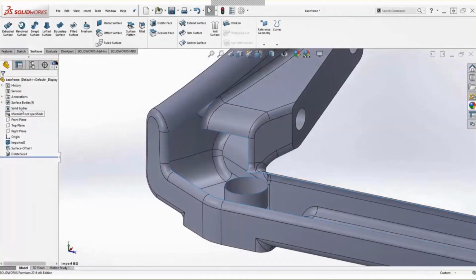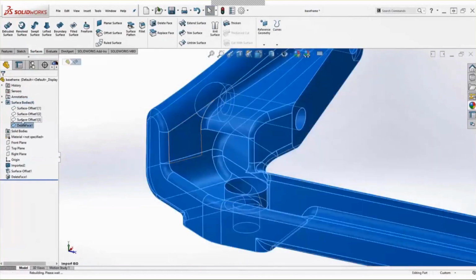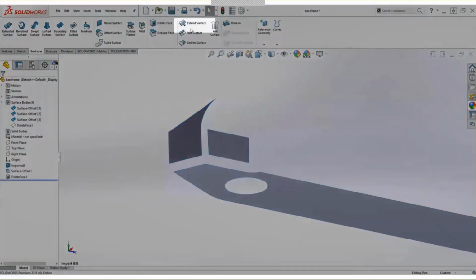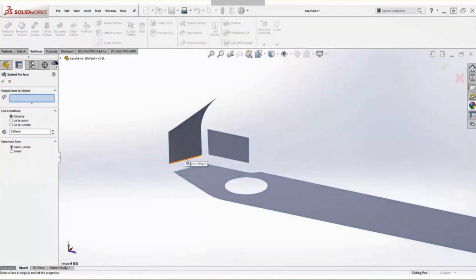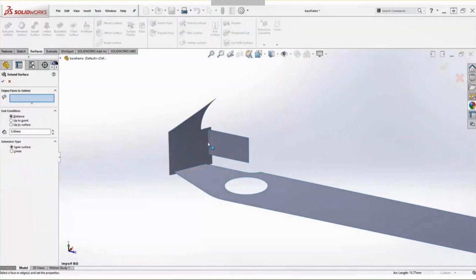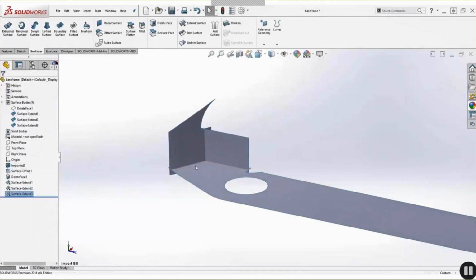And now we need to recreate that hard edge corner. So to do that, we'll need to extend edges of our original surfaces so they all intersect. And we're going to do that using the extend surface command. I only extend the edges that relate to the corner I'm trying to fix so that it'll knit together easily later. And you'll notice that since these are individual bodies, we have to repeat the command a couple of times. And a real quick shortcut is just to continually hit enter after you're done with a command, and then you can repeat the command one time after the next.